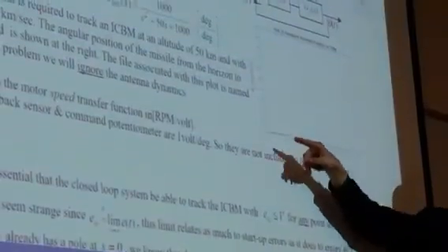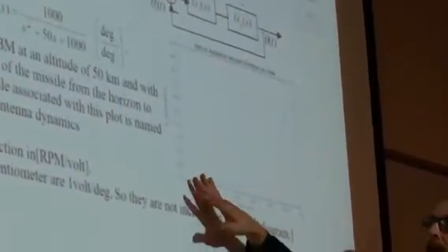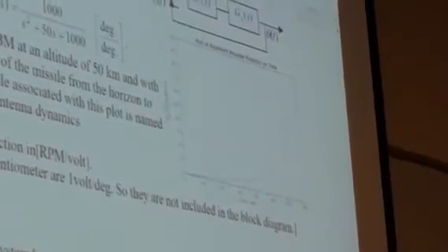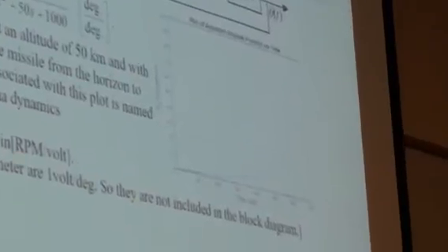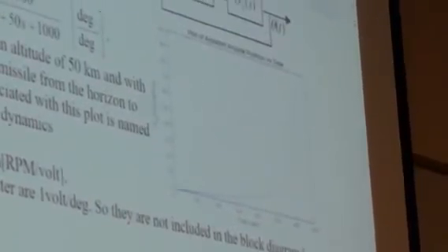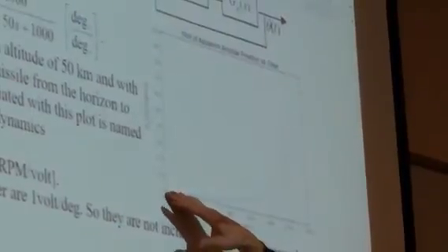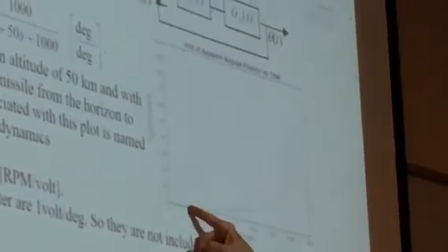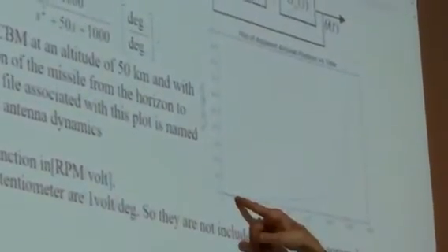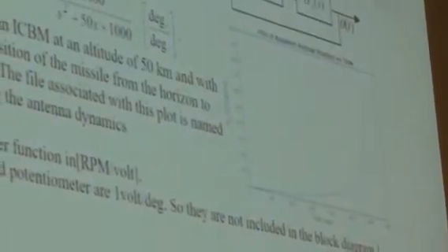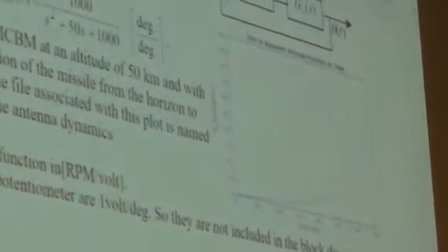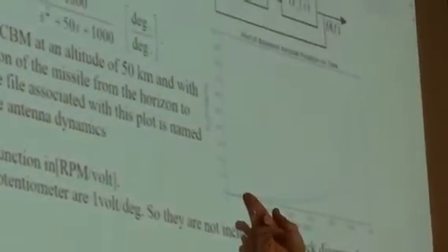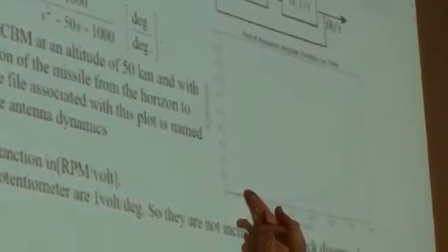It starts with very low angular velocity, and so what you have here is actually a complicated input. This is the command input. You're trying to get the antenna to track that command, so to speak. Okay? So what happens here is you have essentially a ramp, don't you? At this point in time, at 50 seconds in, it's basically a ramp with that slope. So can you track a ramp? Well, sure I can. If I have a type 1 system, I can track a ramp with this much steady state error. Okay? Does everybody know what I'm talking about?